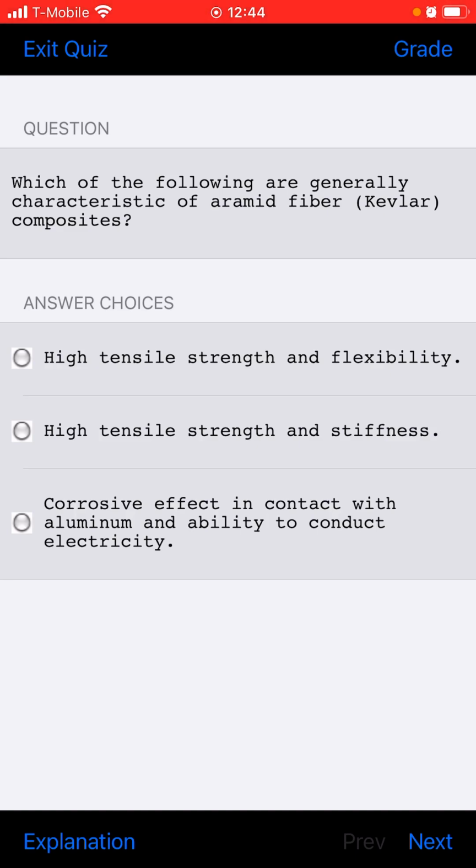Hole filling fasteners, for example MS20470 rivets. That's a hole filling fastener. Hope they don't give me that on the test. They should not be used in composite structure primarily because of the possibility of causing delamination.